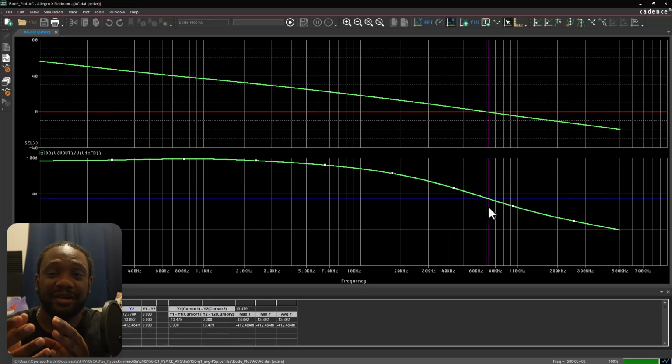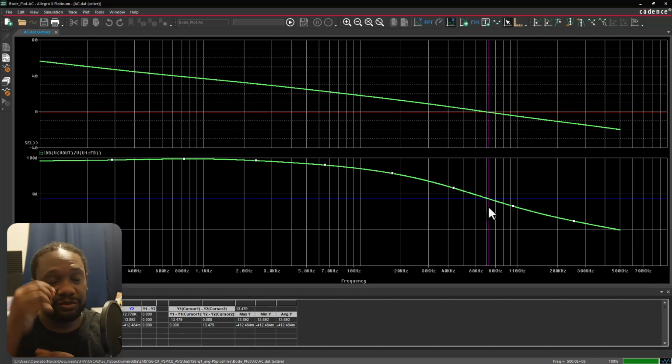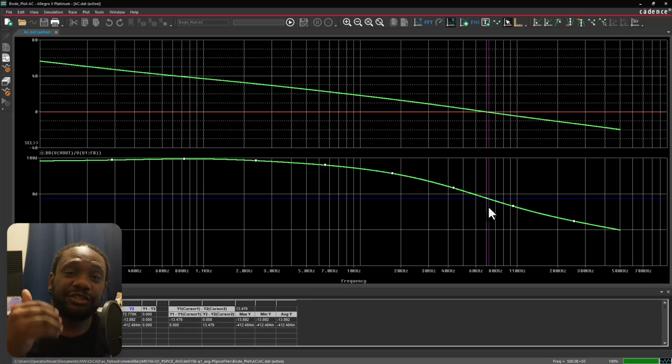This lets me know that as long as I'm far enough away from 180 degrees out of phase, I'm fine. Let's say I get an error and I want to amplify and increase the duty cycle. Well, when you're 180 degrees out of phase, or super late, what you're going to do is decrease the duty cycle when you're supposed to increase it, or vice versa.